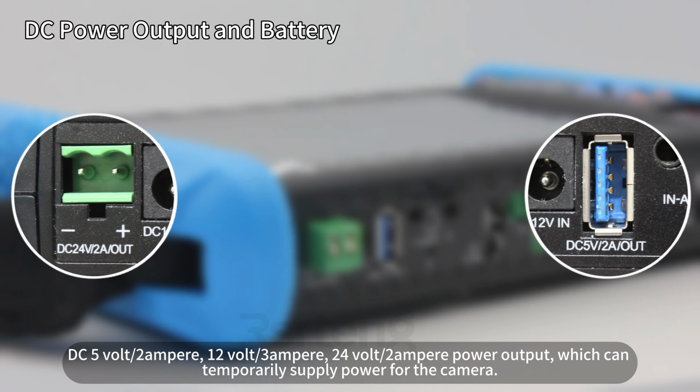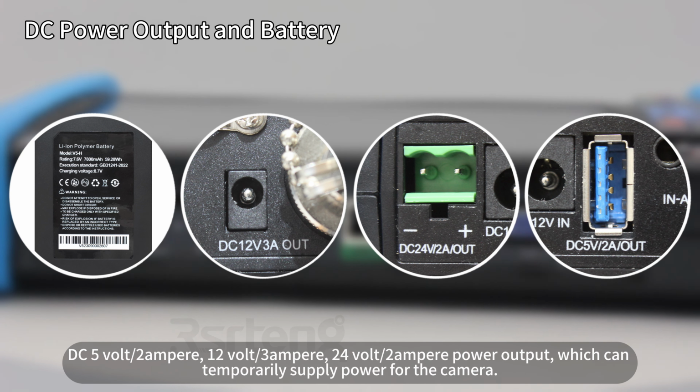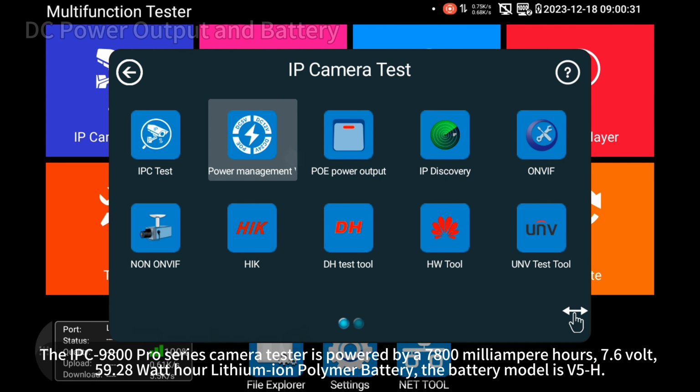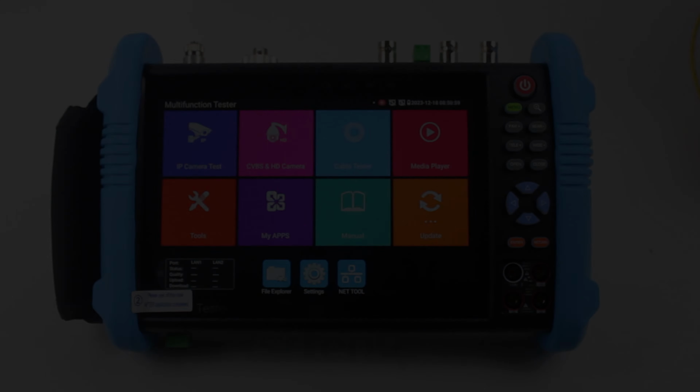DC 5 volts by 2 amps, 12 volts by 3 amps, 24 volts by 2 amps power output, which can temporarily supply power for the camera. The IPC-9800 Pro Series camera tester is powered by a 7800 milliampere hour, 7.6 volt, 59.28 watt hour lithium-ion polymer battery. The battery model is V5-H. The power management application can view real-time data such as voltage and power of PoE, PSE, and DC power.